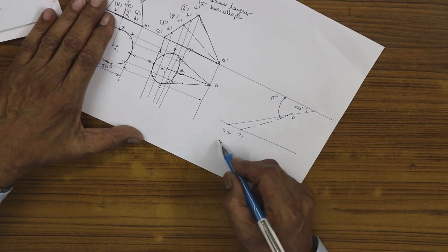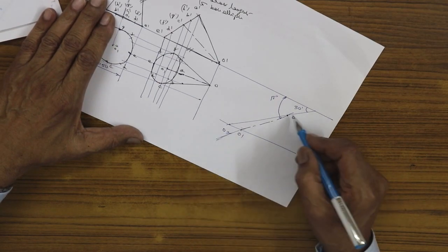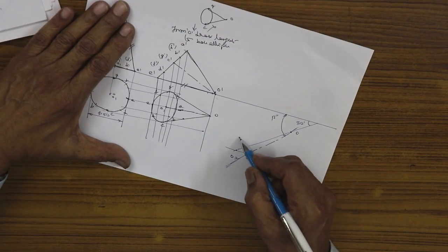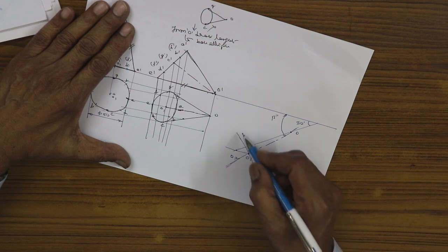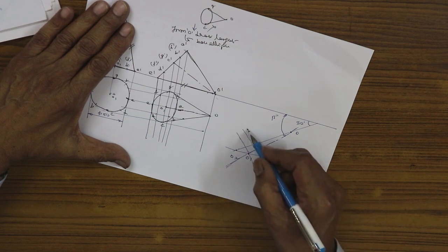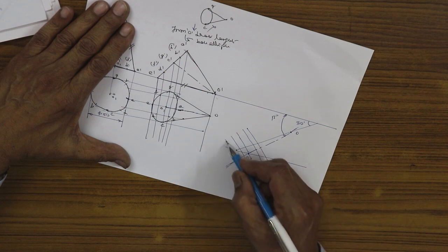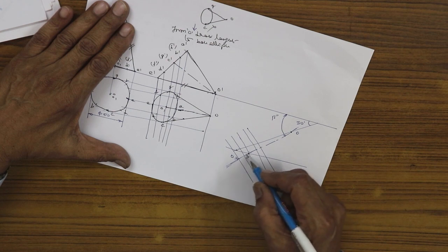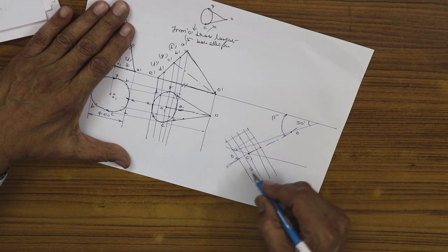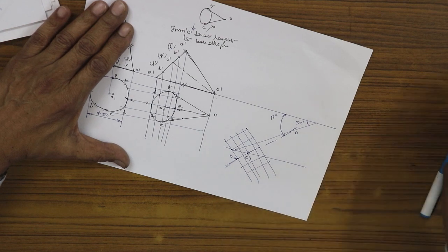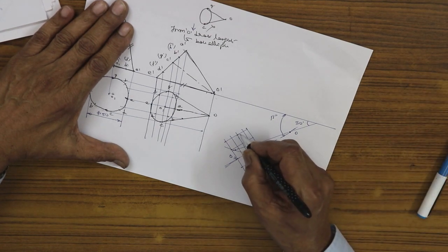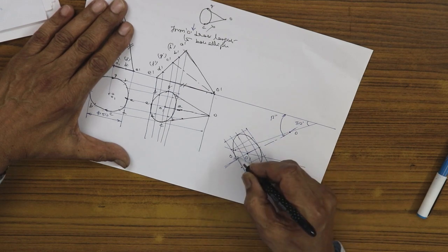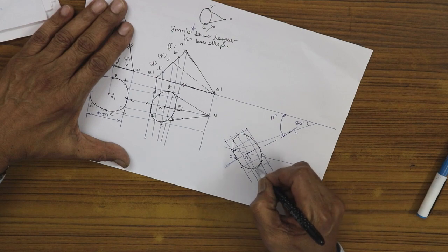You extend the apparent axis, that apparent beta line, backward. This ellipse you have to reproduce by drawing perpendicular to the beta line. These are all the measurements drawn perpendicular to the beta line. All the measurements are taken here, all the grid. You should draw the ellipse grid. Get the ellipse grid here, and complete the ellipse. Take the 8 points and draw the ellipse carefully.